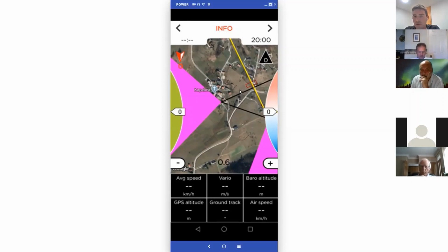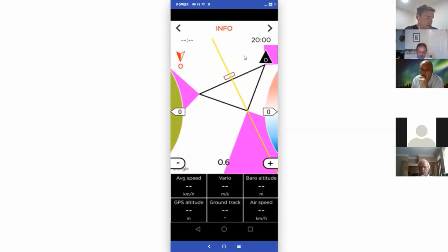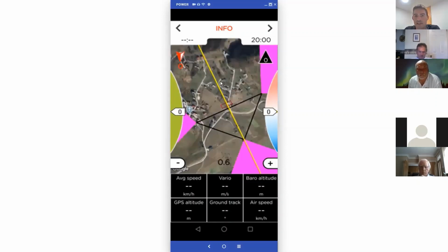So normally, when you fly 20 meters out, which is here, you will check the sector distance when you have to turn. And what is more important, before you start the task, if you are flying parallel to the start line, what you would like to observe is sector distance. Why? Because once you fly parallel to the start line, maybe you're over here flying in this direction, if you check the turning point distance, it will tell you it's still 500 meters. Also, the off-track distance will tell you you're still 400 meters outside, let's say. But your sector distance will tell you only 10 meters from the sector.